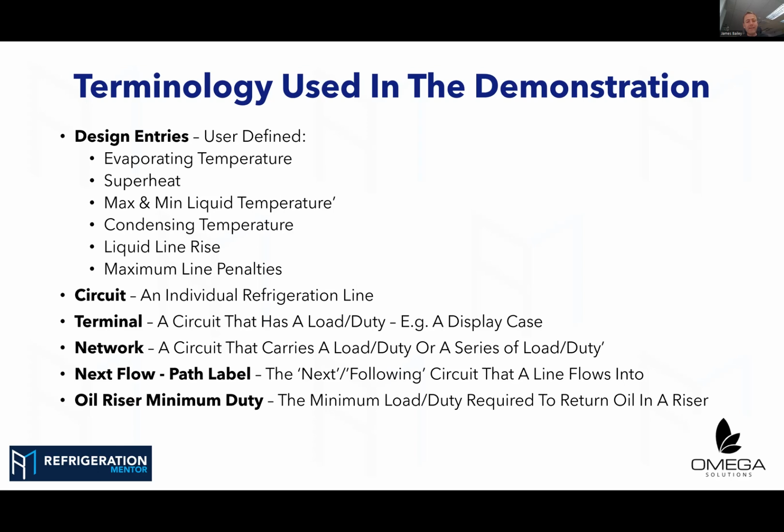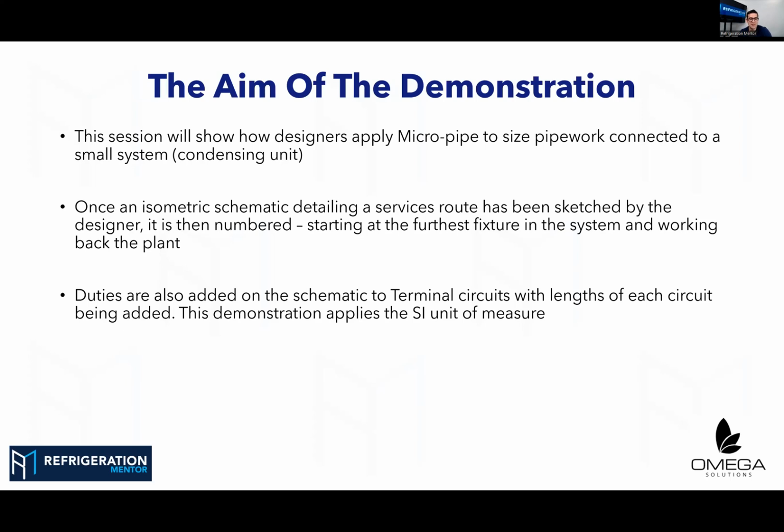I've actually seen what's happened with bad design. The amount of gallons of oil that can sit within a system is absolutely astronomical. In a worst case scenario, that will eventually remove surface area of the coil, so the display cases or cold room evaporators have to work harder to achieve their desired temperature. Yeah, and that's something you don't really think of because you don't see the oil, and it only comes up after a few months. This is it, Trevor. We don't have X-ray vision. We can't see what's going on in those pipes.